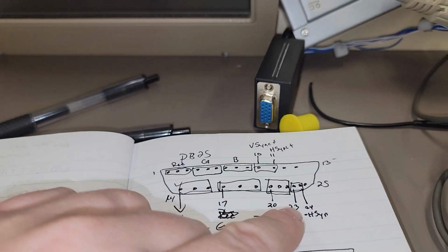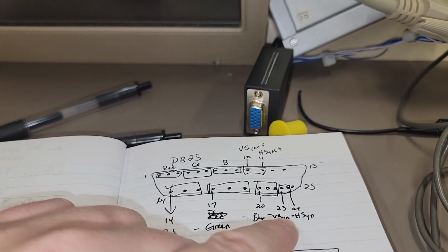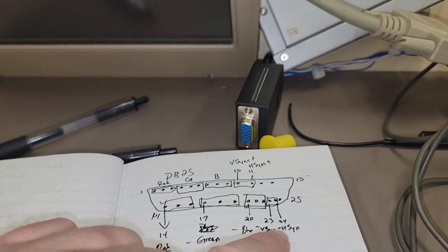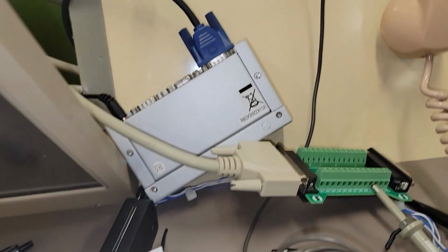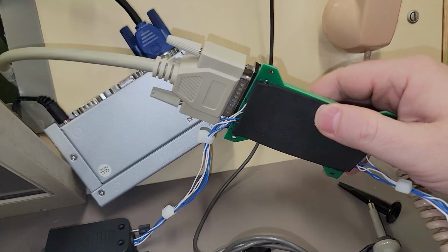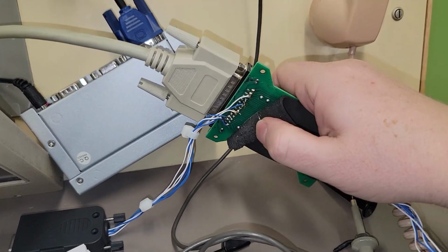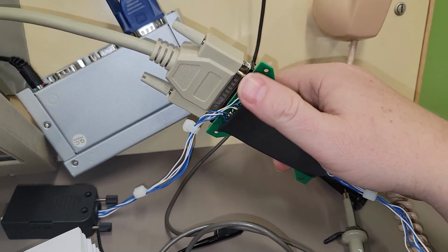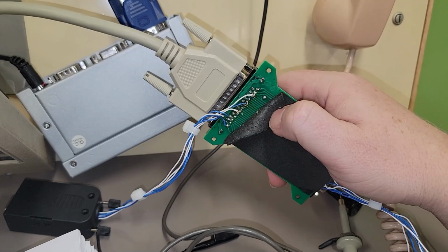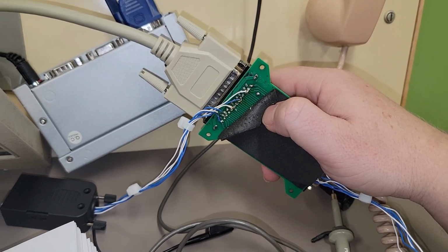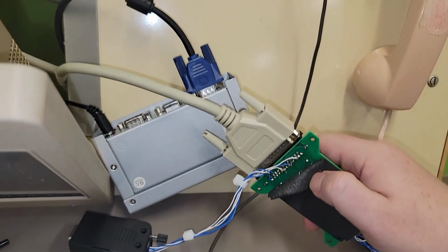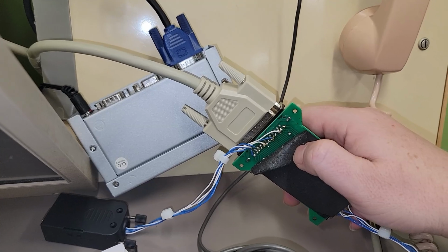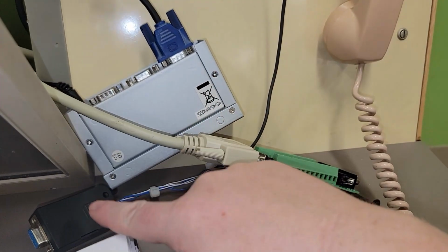So now, for all intents and purposes, I actually have to tap off 23 and 24 for my horizontal vertical sync, because this is where I did the modification on the back side. There goes the input. That's all good. I tap off of an RGB, the horizontal and vertical sync, and additionally I'm tapping off a ground, providing it to this right here.